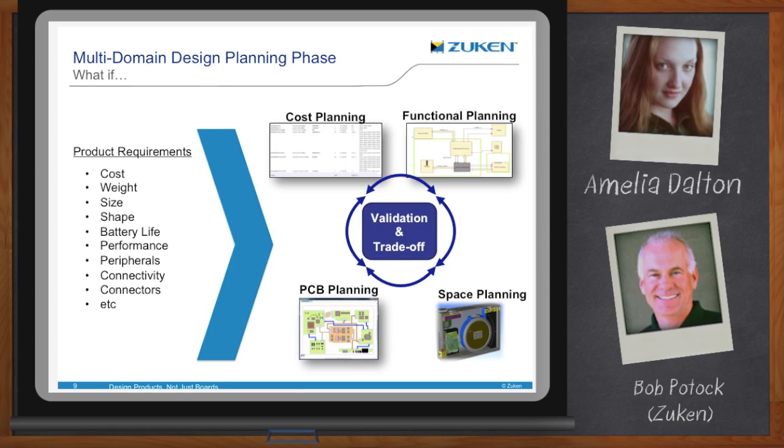So when we look at the 4 domains that we're looking at right now, cost planning, functional planning, PCB planning, and space planning, they all have to be connected because we need to validate cost targets, weight targets, size targets, and we have to make trade-offs. Will the board fit into the enclosure? Can I hit my cost target with this particular part, or do I need to change out the parts? And if I change out the part, do I compromise functionality? These are all intertwined trade-offs that are best done at the planning phase as opposed to the design phase.